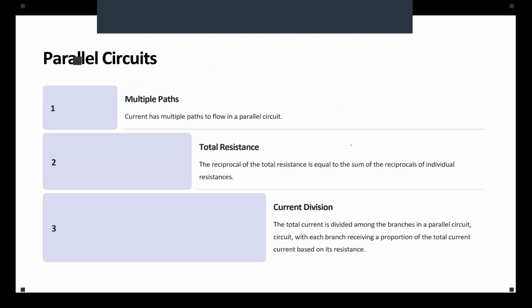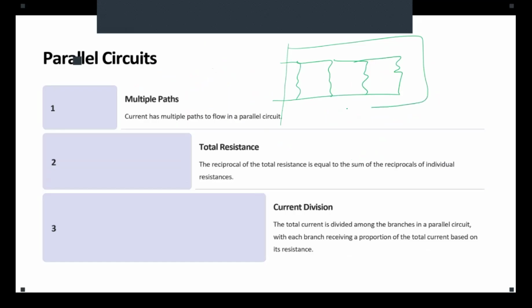Now, if we have resistors in parallel, what happens then? If you have the parallel of some resistors, you can calculate the R equivalent based on the inverse of those resistors. It comes from the KCL. You run a KCL at this node, and you will end up with this equation. So it's going to be 1 over R1 plus 1 over R2 plus all the others, the inverse of all of the resistors. Are we good?